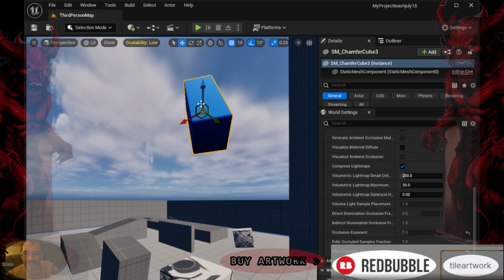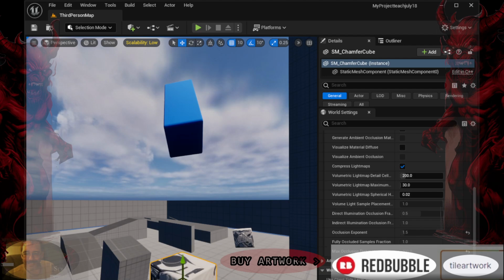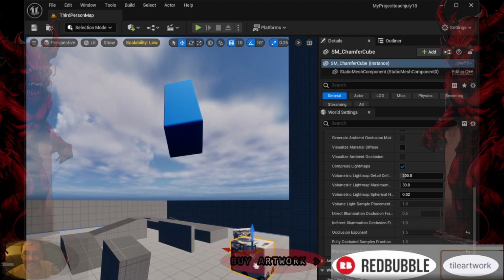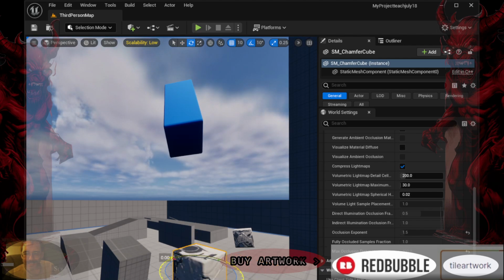Local coordinates. In local gizmo mode, the manipulator handles represent transformations relative to the object's local axis system. This axis system is aligned with the object's orientation. For instance, if an object is rotated, the local axis aligns with the object's orientation after rotation. This allows you to manipulate the object without altering its global orientation.